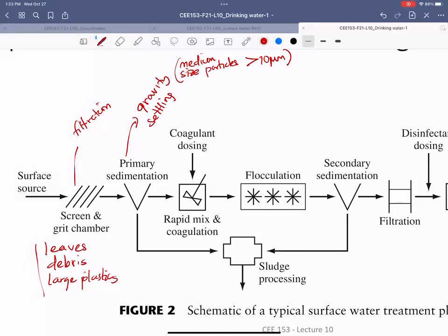It's not the size, because if you have 10 micron size of foam particles, it will never settle, because that's very light. So I'm assuming soil, anything mostly greater than 10 microns, or think of the size of hair. Hair size is 100 micron. So anything around that size will all settle out. Anything smaller than that, less likely will settle.